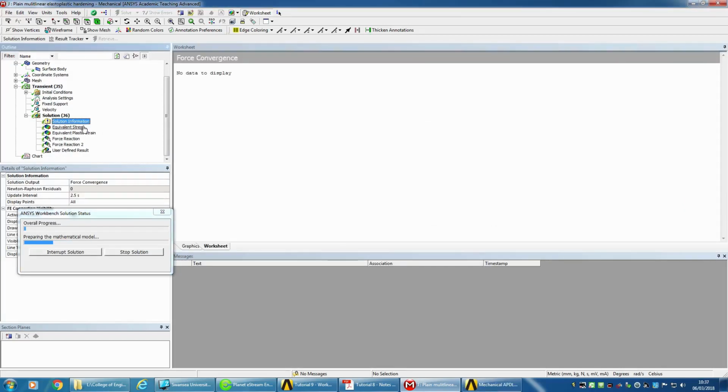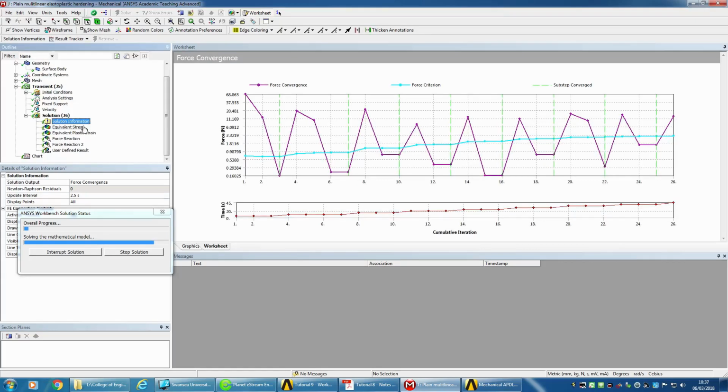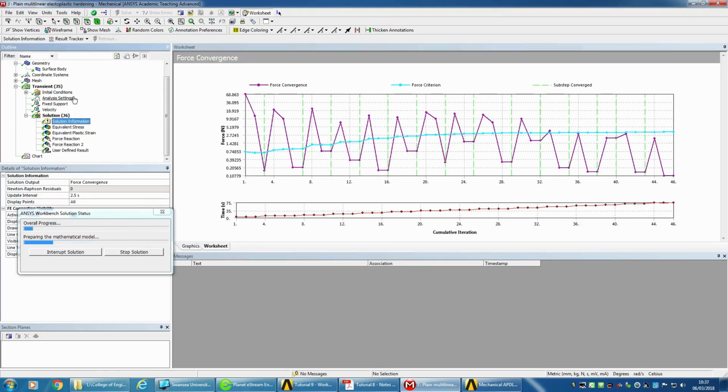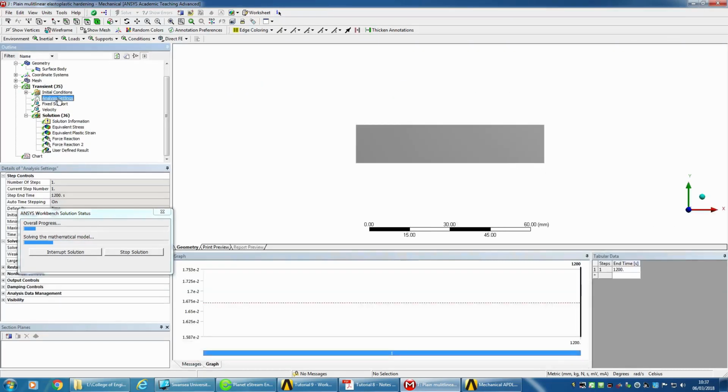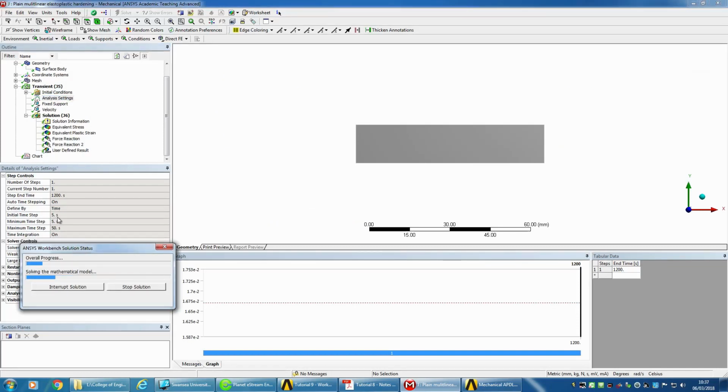Luckily this one I did run earlier, so I do know it'll run. With the time steps of this as well, we're using quite coarse time steps, and the time step size that you choose can have an influence on your final solution. So if you're doing a sensitivity analysis on the model, which you're asked to do anyway for the computational modeling part at the end of the course for C3, there's two things you need to check here: time step and mesh size. You need to do a sensitivity study a little bit on both of them.